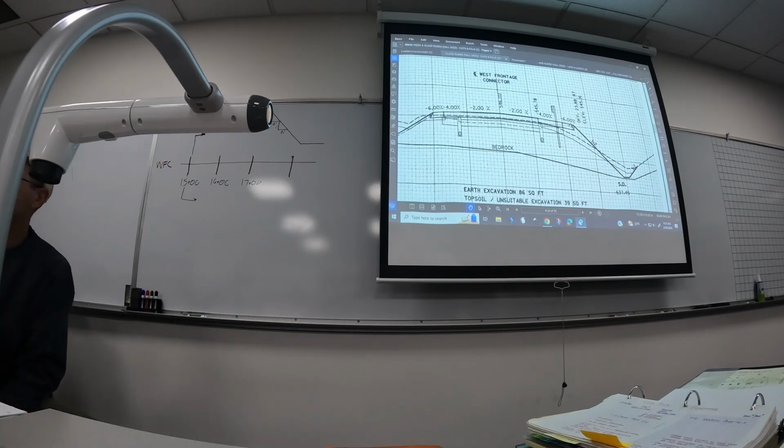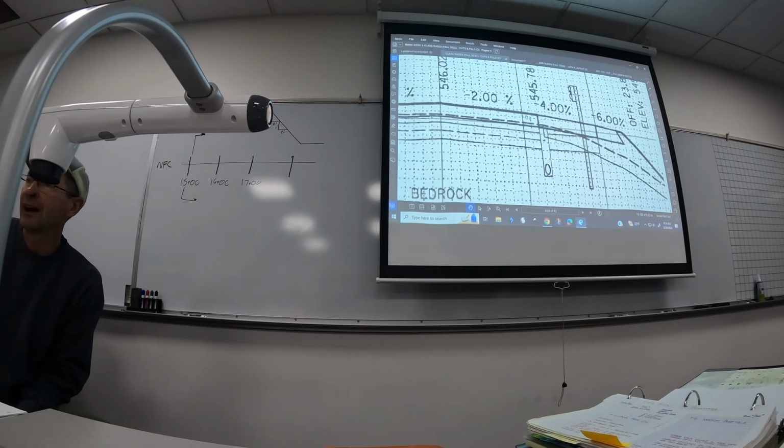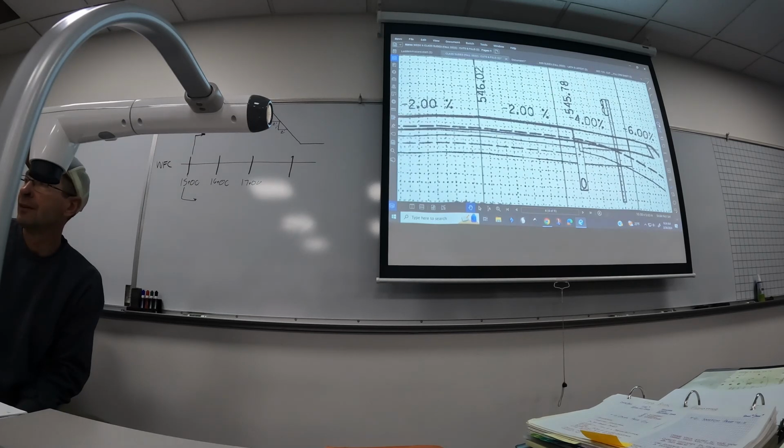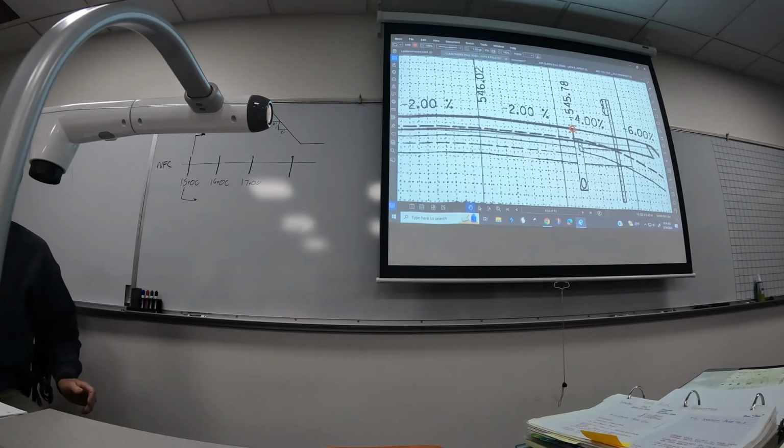So we have the ability to now basically take this elevation, we can get to here, we can get to here, we can get to here. Now what 2 pieces of information do you think I need to tell the paving contractor where this point is? If the contractor said, I need you to do AEC 125, construction staking. If I needed our group to stake that point, do I have enough information for us to calculate it as a group here? Could we do it? Paving contractor says, I need you to tell me what elevation that outside edge is at.